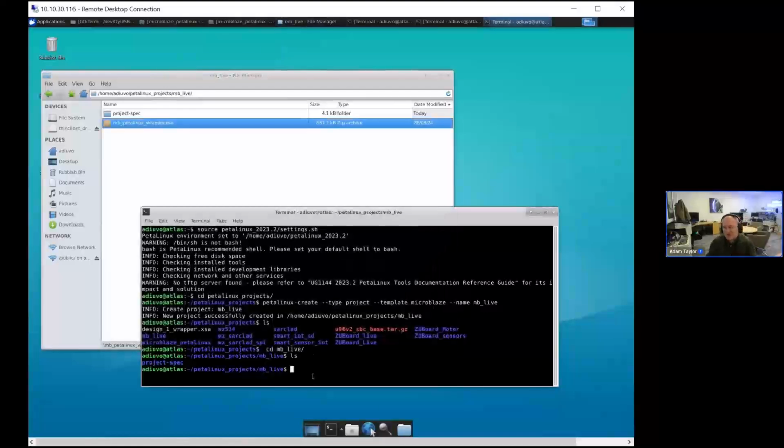And then I'm going to run a command to do the PetaLinux config, petalinux-config. What this is saying is you can have this file anywhere in your file system, but actually in this case, I just want to get to it simply, which is why I just put it one level above. And get hardware description equals... Let me just check I've spelled that right, because I always spell that wrong. Get hardware description petalinux-config.